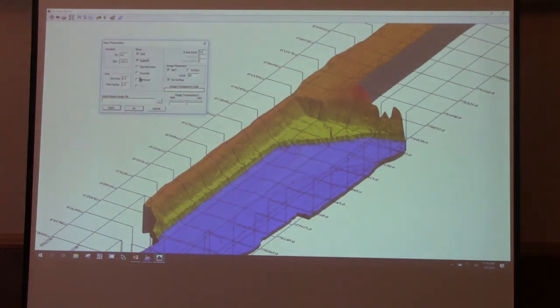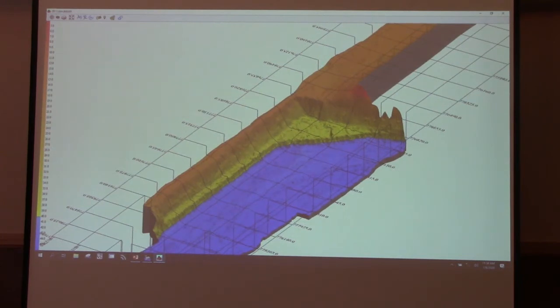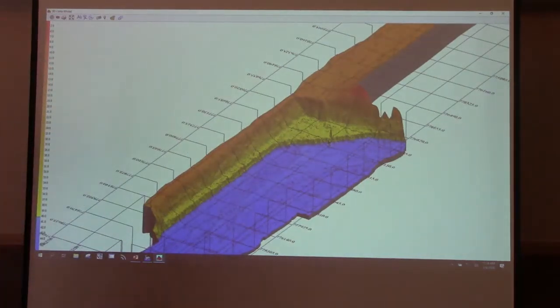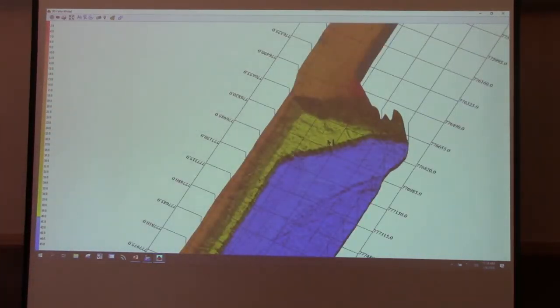You put a legend on, put a channel on if I had a channel. Contours, if you apply contours, you'll start to see gray, whatever the contour interval is. So every so many feet down here, you'll see a darkened line through the different contour layers so that you can actually differentiate that in the images. It helps a lot when you're drawing these things for customers especially, and you want to show something, you can put a 10-foot contour in there, a 20-foot contour in there, see dark lines in their 3D images.